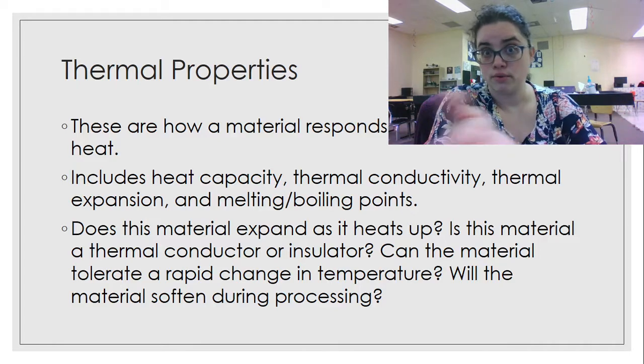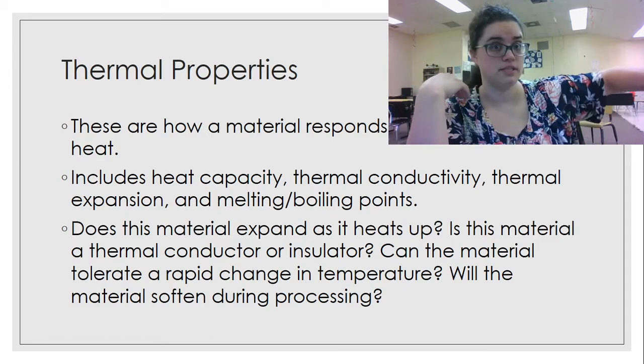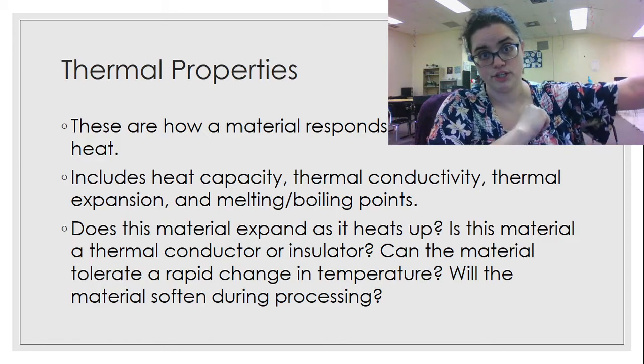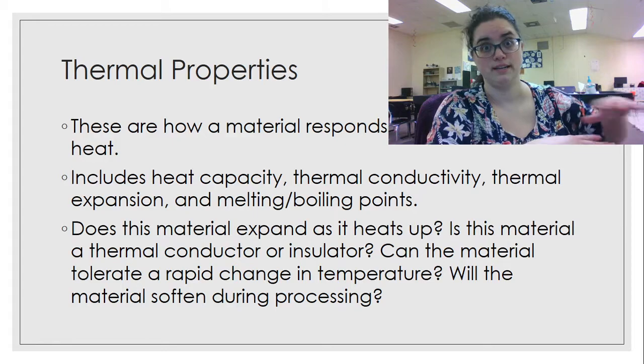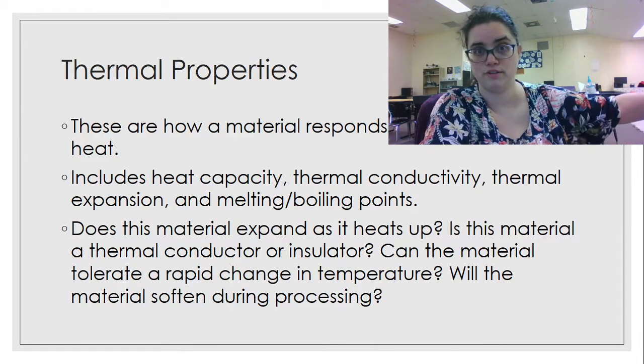Will it soften during processing? You might want it to soften, or you might not. If I'm running metal through a machine that's supposed to stamp it out or bend it into a certain shape, and as I'm running it through the machinery, it heats up, it might soften, it might deform, it might not hold whatever shape I try to make it.